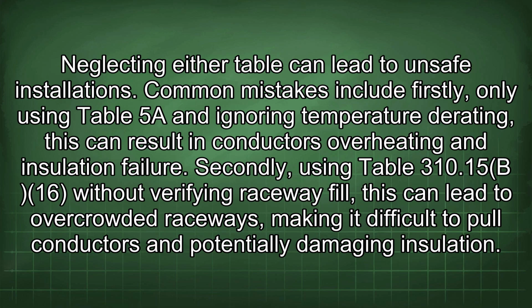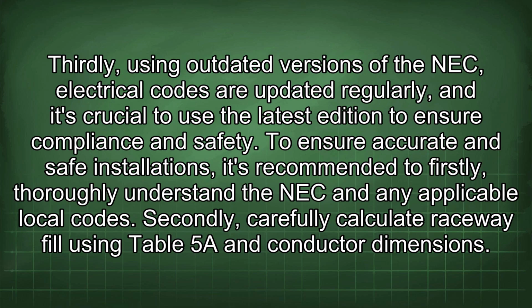Secondly, using Table 310.15(B)(16) without verifying raceway fill. This can lead to overcrowded raceways, making it difficult to pull conductors and potentially damaging insulation. Thirdly, using outdated versions of the NEC. Electrical codes are updated regularly, and it's crucial to use the latest edition to ensure compliance and safety.